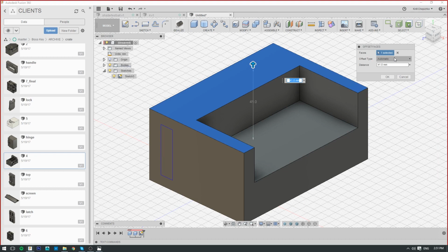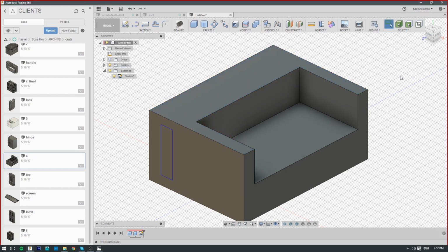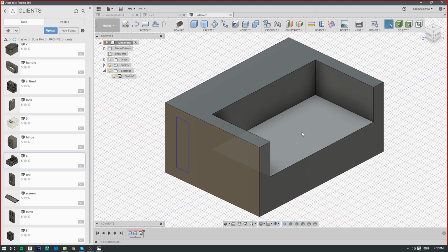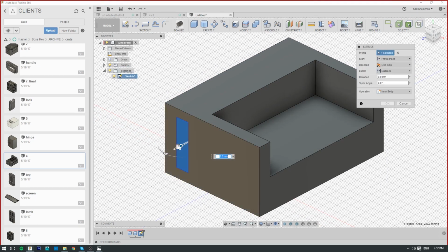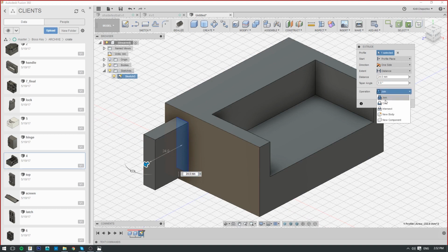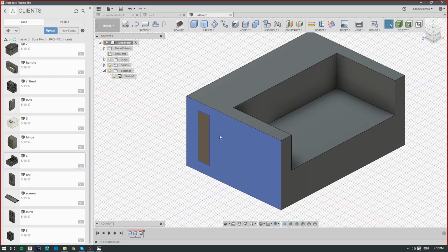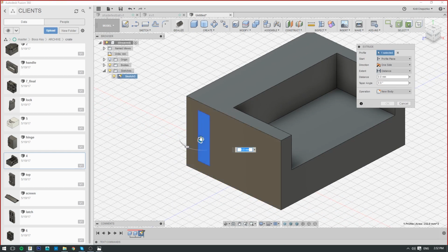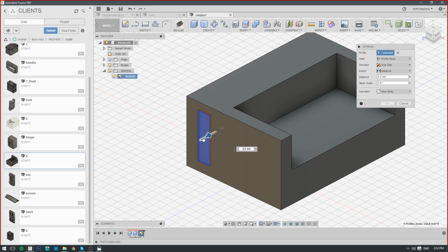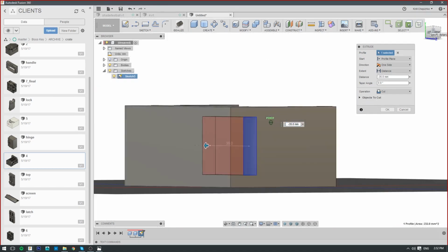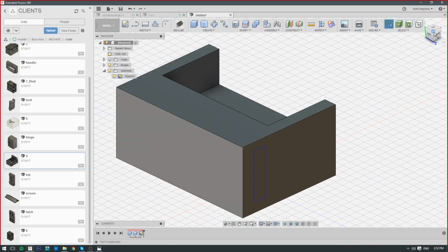And also, if I haven't explained that before, you can choose between modify existing feature, new offset, or automatic. Usually automatic works fine, like you'll figure out the way. And then you can also press pull the sketches, and that's when you control whether it's joining, cutting, or new body. But extrude, and actually it's good to mention that press pulling also works inward as well, right? So you can cut with that.